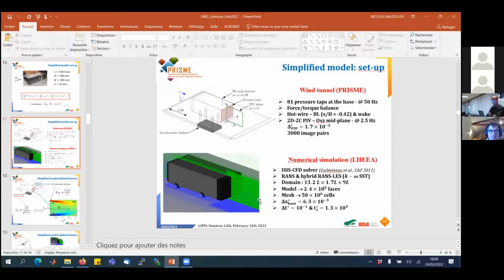And my second point, which may be quite important in a few years: there may be a major difference between the aerodynamics around a thermal combustion car and the aerodynamics around an electric car, simply because when you cool down the battery pack in the electric car, maybe you can use that flow that you cool with to control the wake, or to address it on the back side of the car, such that you manage to either reduce the drag or control the separation on the backside.